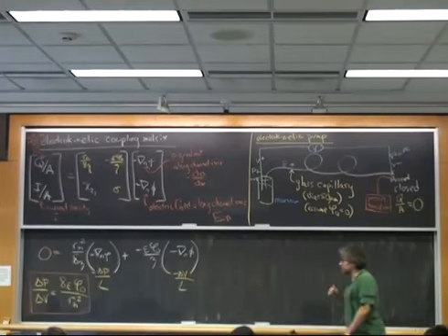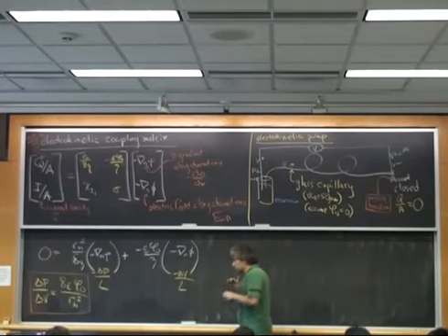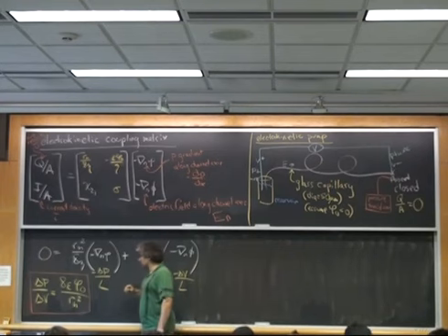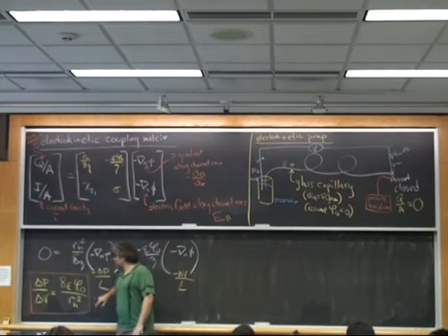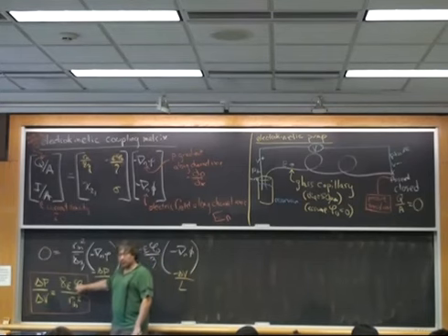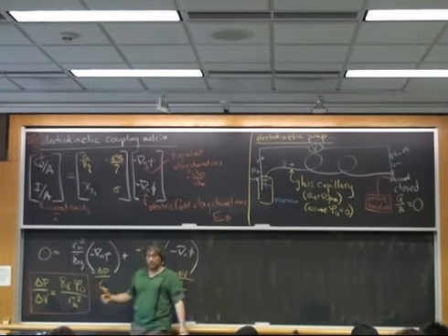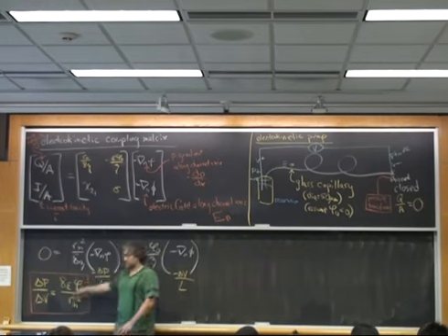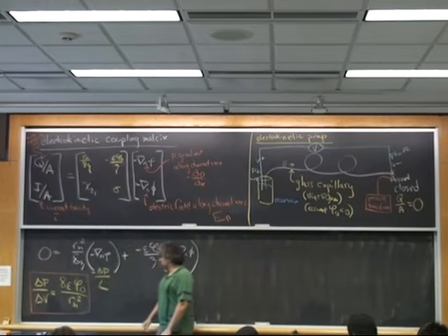So if you want to make electrokinetic effects important, at least interpreted as a function of voltage, you want to use a fluid that has a high electrical permittivity. So high electrical permittivity makes this happen. Viscosity doesn't matter. Interfacial potential matters, right? If my interfacial potential went to 0, I would have no electrokinetic effects, no pump.